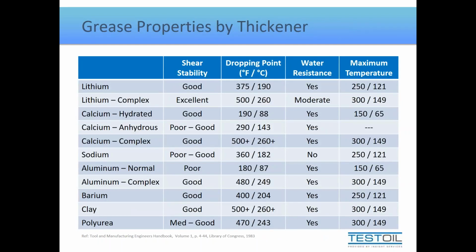And if you scroll over to the right-hand side of the table, you will see the maximum operating temperatures, and you will note that there is a greater than 50-degree difference between the dropping point and the maximum service temperature. So that rule of thumb doesn't necessarily hold very true. So I would always, of course, refer back to the product data sheet for the recommended maximum service temperature for any particular grease.